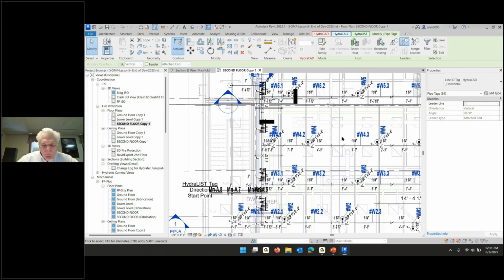But right now, my A1 was at the south end of that cross main, and it listed A1, A2, A3 up to the north end, then came back and went 5, 6, 7, 8, 9, or whatever to get down to the riser manifold. Also, I moved up and to the right all of those branch line tags.